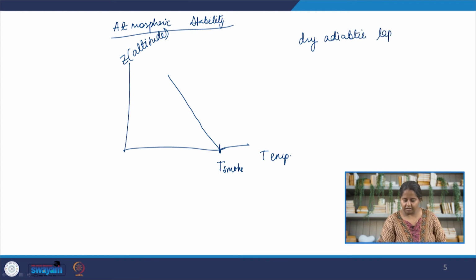Now again there are two assumptions here. First is that the smoke is dry, it does not have any moisture, which may or may not be the case. For example, steam engines were releasing steam along with other contaminants. If you have steam coming out, or if you have combustion, where one of the combustion products is moisture, then you will have to use either the wet adiabatic lapse rate, or you'll have to figure out what your adiabatic lapse rate is.